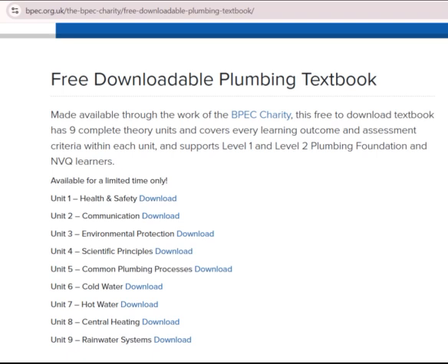Flue types used with gas and oil-fired boilers and appliances. All appliances that burn gas, oil and solid fuels need a flue system to evacuate the products of combustion away from the dwelling. The basic principle is to create an updraft or a difference in pressure, whether by natural means or whether by the use of a fan, to eject the combustion products safely to atmosphere. There are two basic designs: room-sealed flues, open flues.